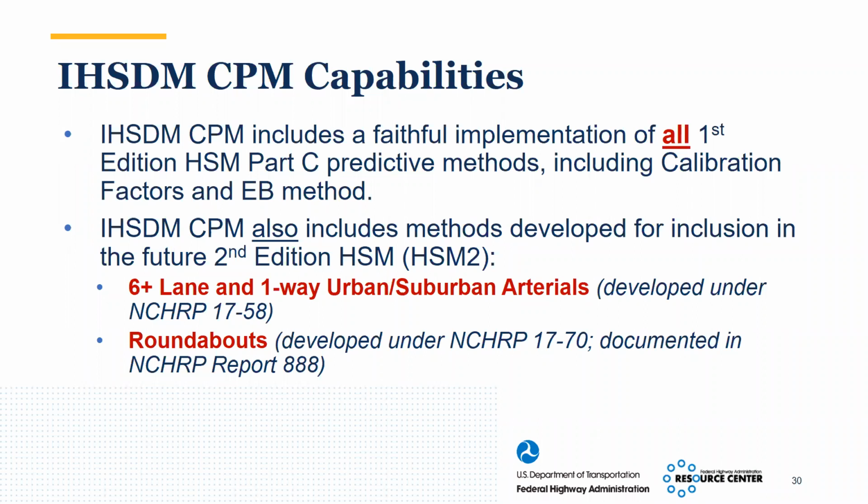Each tool has certain limitations, certain advantages or strengths. Here with IHSDM, as with some of the other tools, one advantage is that IHSDM includes a faithful implementation of all of the first edition HSM Part C predictive methods, including the calibration utility, which is part of what Hassan just mentioned, and the empirical Bayes method to factor in historical crash data.